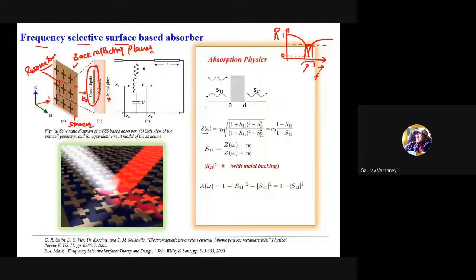Just think, within this frequency spectrum, reflection is already approximately zero in this particular frequency band f1 to f2. Now if we mitigate the transmission within this frequency range f1 to f2, so that transmission becomes zero, or mod of the S21 parameter squared becomes zero, then this whole structure can be utilized as an absorber.